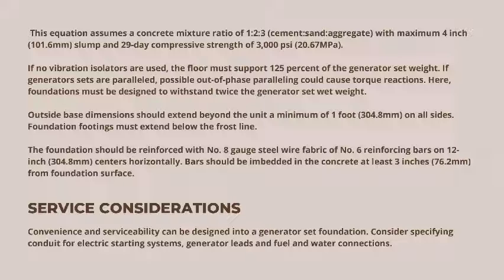If no vibration isolators are used, the floor must support 125% of the generator set weight. If generator sets are paralleled, possible out-of-phase paralleling could cause torque reactions. Here, the foundation must be designed to withstand twice the generator set wet weight.